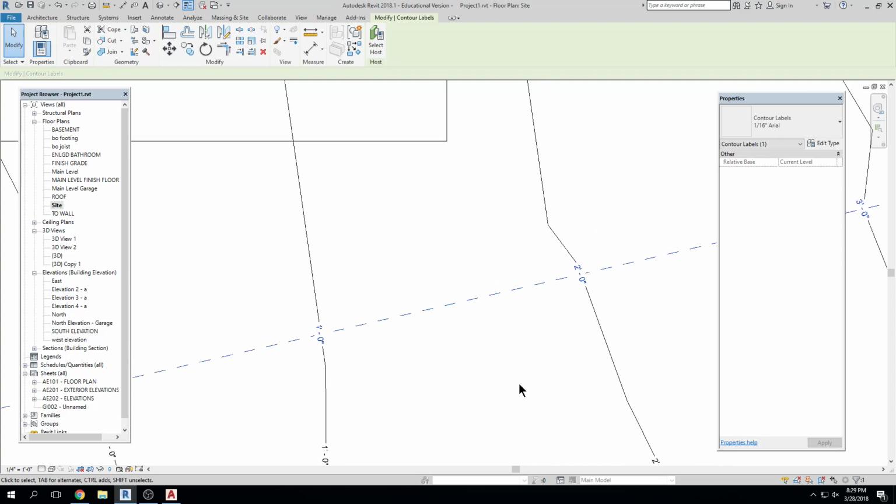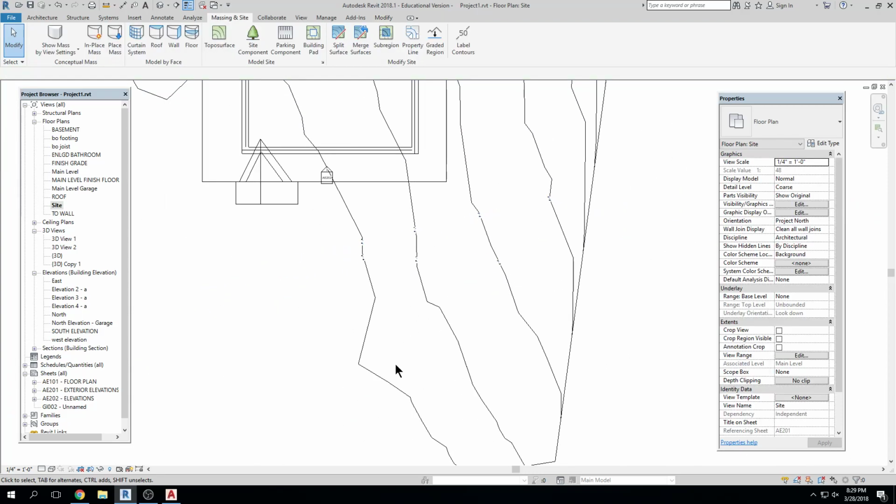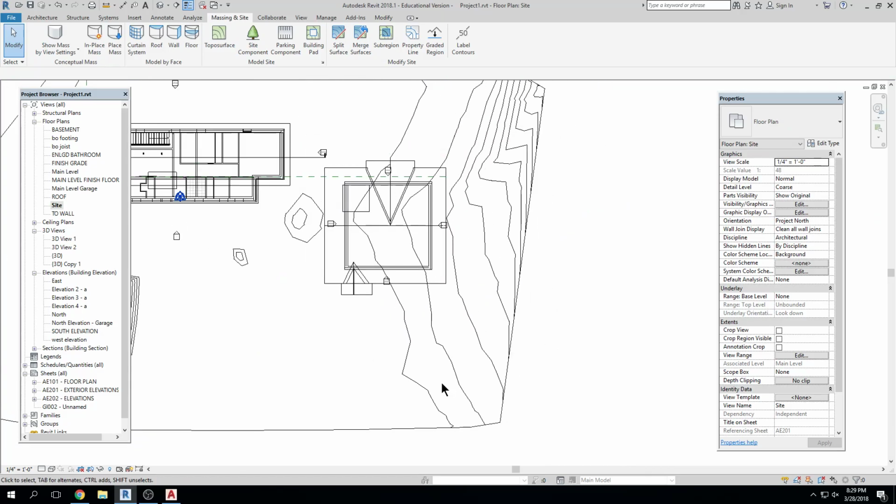So when you have a linked file where one file is maintaining its level above sea level and you have another file that is referencing that, I can still read the 4850, 4855, 4860 or whatever on my topo surface, right? So that I can see where all the levels hit, okay? And your elevation markers, are those going to base off of the... That's a good question. So when you link your files together, you can choose that. You can choose to say, no, I want them to be like 1 foot, 2 foot, 3 foot, 4 foot, or you can choose to reference the actual topography and have it read like 4850, 4855 or whatever you want it to do. Cool. Yeah.